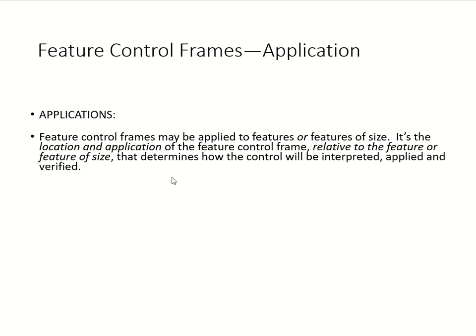So you go with the geometric character, you go with the tolerance, followed by the datum. And each one of them has a material condition modifier, either MMC or LMC, and if there isn't an LMC or MMC, you're just going to go RFS without the symbol. So things like that. And of course, this control frame we're going to apply to the features on your part. So that's all you need to know.